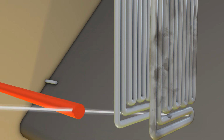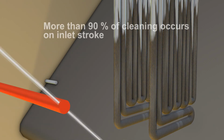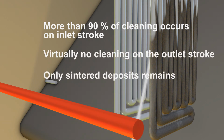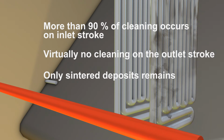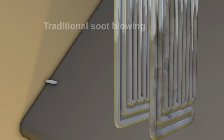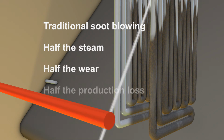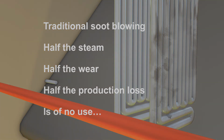Steam soot blowing is normally performed with rotating lances, cleaning the boiler heating surfaces with high-pressure steam. Cleaning is performed when the lance moves into the boiler and when it moves out. A known fact is that nearly 100% of the cleaning occurs on the first pass of the steam jet, and almost no cleaning is achieved on the return. Classical steam soot blowing therefore means that half the steam, half the wear, half the disruption time, and half of the production loss is of virtually no use.